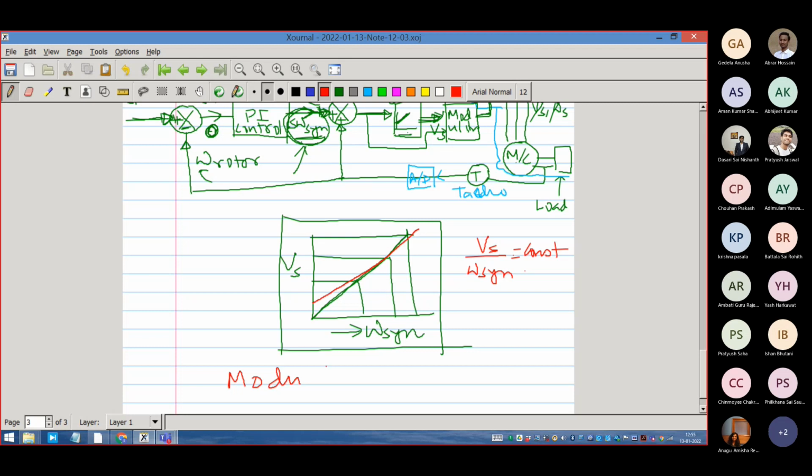So you know that now our study will be concentrating on, from next class, what is an inverter and what is a modulator. These two are things to learn. Control system part will leave aside. Control system will assume that it has been properly designed. Though if it is not properly designed, you will see speed is hunting. Speed is never coming to the reference value. It is going high and high, low and going high and going low. It is continuously hunting. Okay, this is called instability. So you will see that.